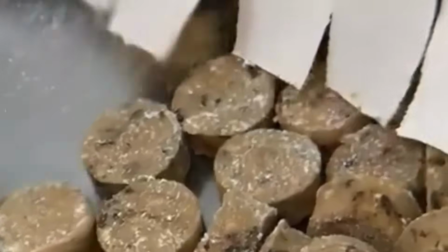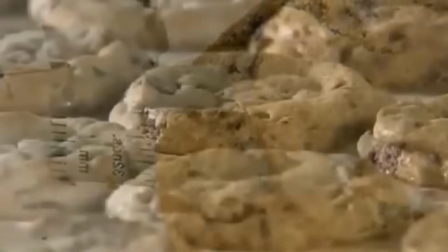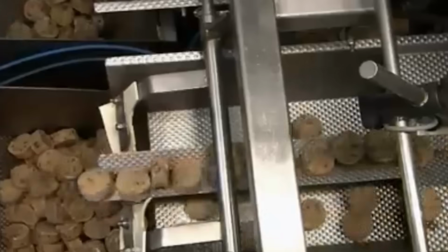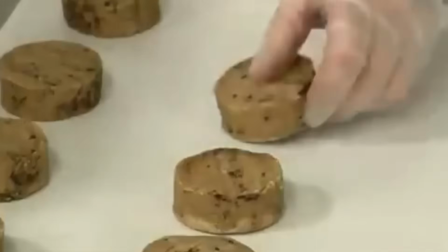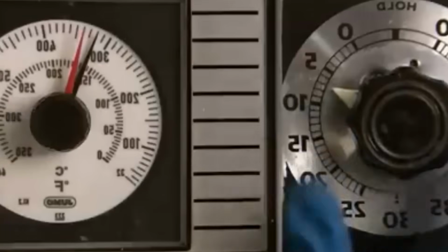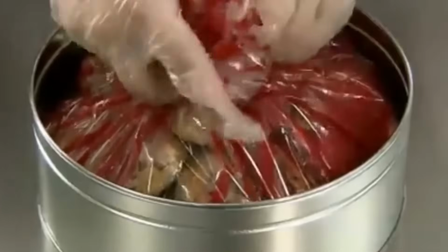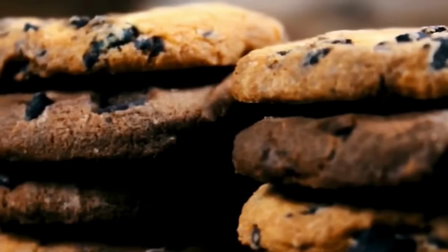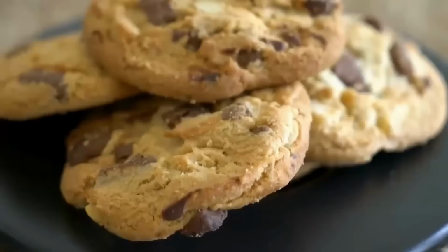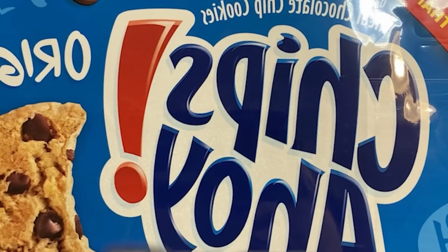Approved cookies move to the packaging station via a system of vibratory conveyors that align and group the cookies into required configurations. For multi-pack packaging, cookies are grouped into stacks using rotary collators and staged for wrapping. Individual flow packs are created using horizontal form-fill-seal machines. Film is pulled from rolls, shaped around each cookie group, and sealed using heated crimp jaws operating at 130 to 150 degrees Celsius. Modified atmosphere packaging may be used with nitrogen flushing to reduce oxygen and delay lipid oxidation.